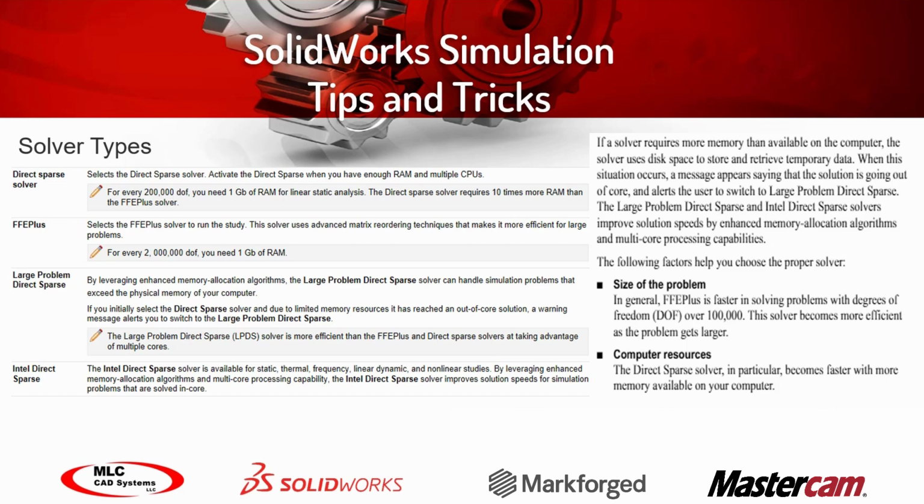I've got a little bit of information on the solvers. My rule of thumb here is I just leave it on automatic and let the software decide which one it is. And I don't have a lot of issues with that. The different solvers basically take different amounts of RAM. That's the biggest difference between them. And there's information in the manual in the appendix. And I'm sure you can find this documentation on the SolidWorks knowledge base as well.